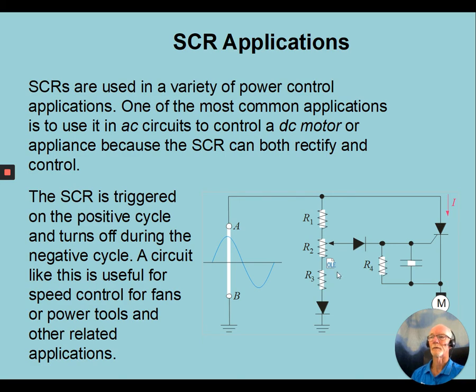The other disadvantage with the silicon controlled rectifier is that you can't turn it off. It actually automatically turns off when the current through it reaches a minimum. So, for example, if we were using an AC circuit, when the current crossed over zero, the device would turn off all by itself, and we would have to turn it on at the next half cycle.